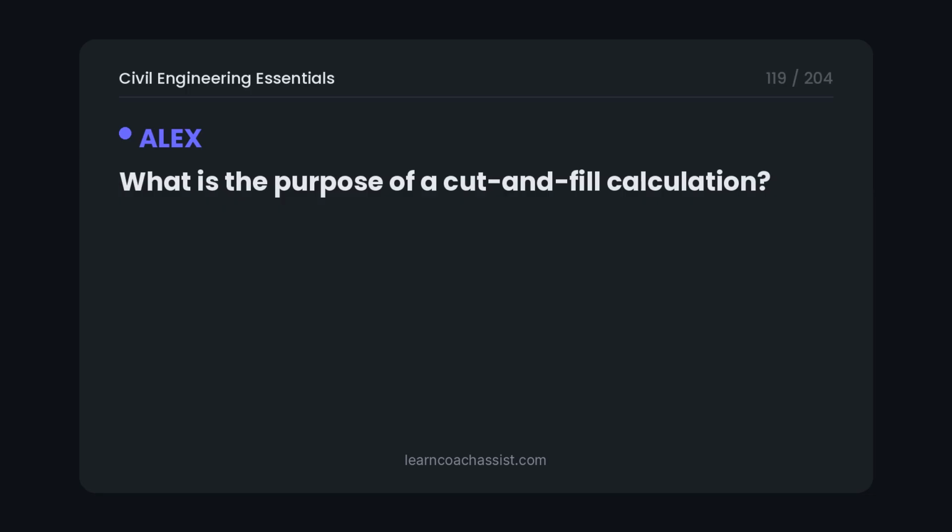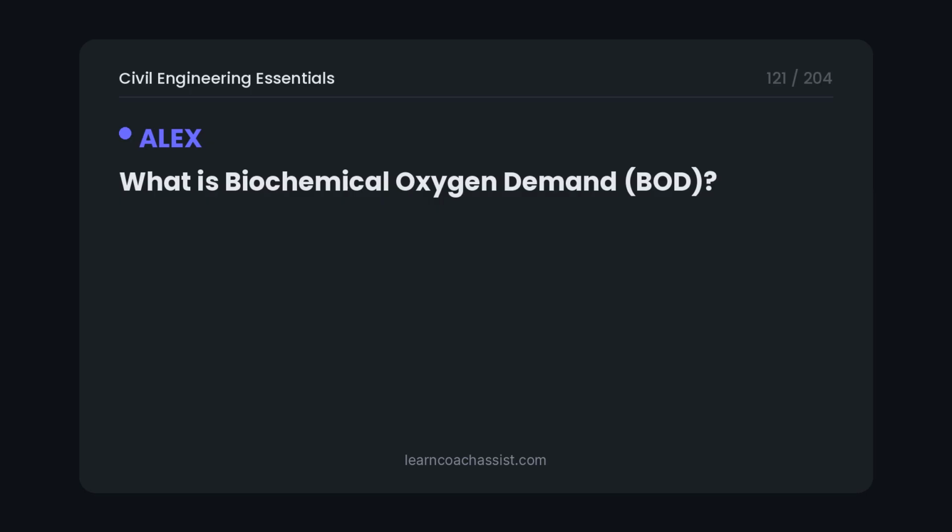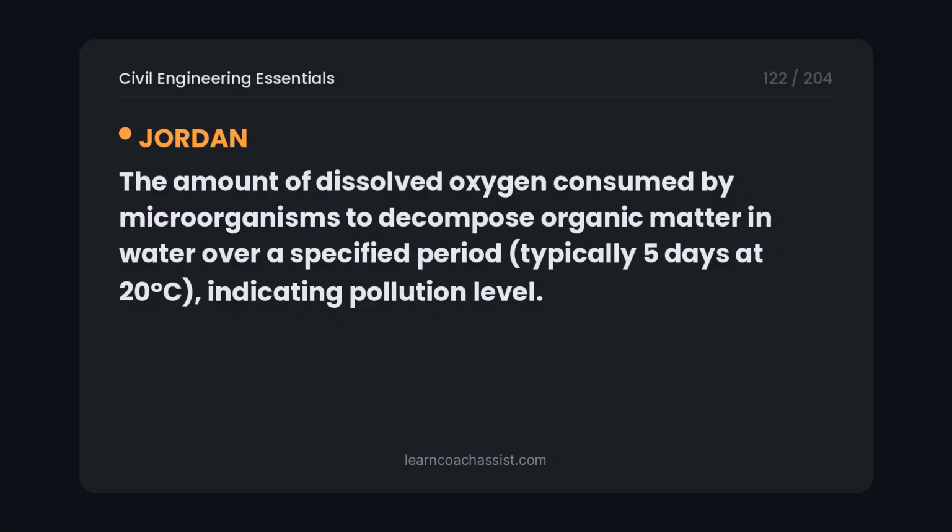What is the purpose of a cut and fill calculation? To estimate the volumes of earthwork required to be excavated, cut, and placed, fill, to achieve a proposed grade, optimizing balance to minimize hauling costs. What is biochemical oxygen demand, BOD? The amount of dissolved oxygen consumed by microorganisms to decompose organic matter in water over a specified period, typically 5 days at 20 degrees Celsius, indicating pollution level.